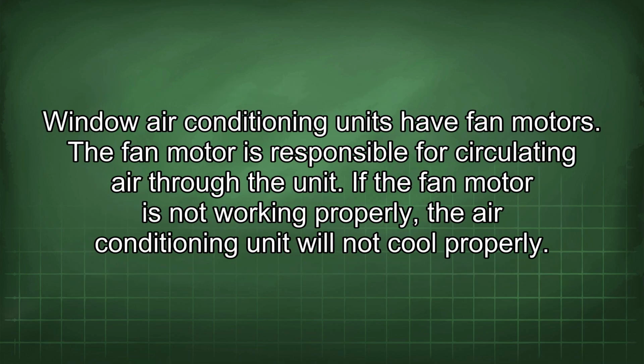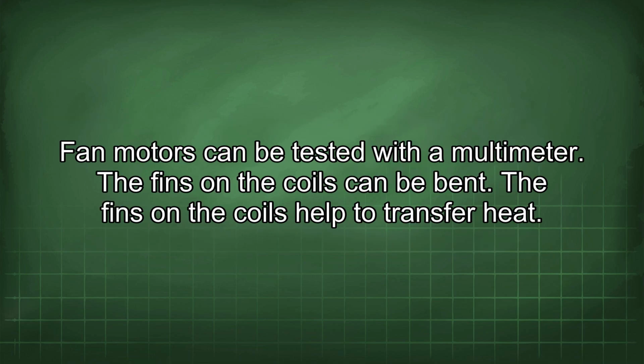Window air conditioning units have fan motors. The fan motor is responsible for circulating air through the unit. If the fan motor is not working properly, the air conditioning unit will not cool properly. Fan motors can be tested with a multimeter.